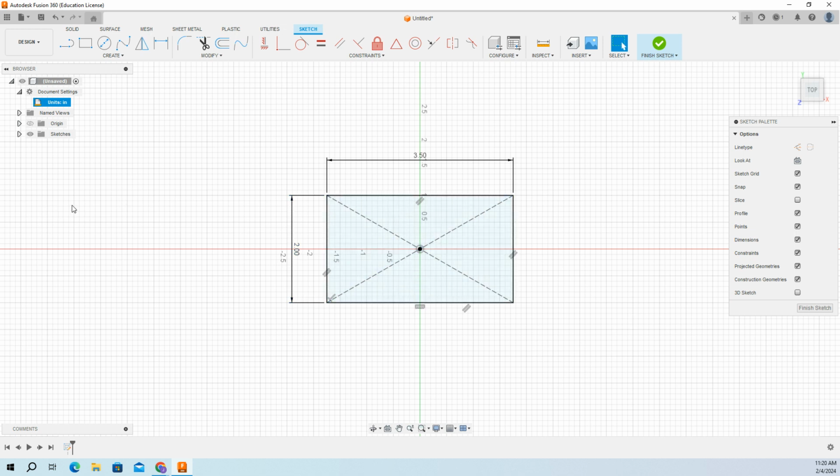All right, now this is why I like the center line, so I know where to draw stuff. But now we have a circle that's connected to it. The middle circle has the same midpoint as this, and the diameter is going to be 1.5. And then we have the outside looping circle with a radius of 1.37.